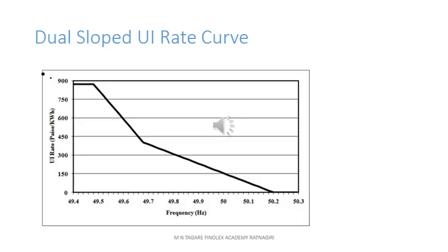So when the grid has surplus power, that is the frequency is high, if you pour power, this is of course only for unscheduled power. For scheduled power the rate is already fixed, but unscheduled interchange will be dealt with like this. So you will not be paid when there is excess power, and immediately you will stop your generator pouring more power. Similarly for the customer, if the frequency is very high, you will encourage your customers to take more power.